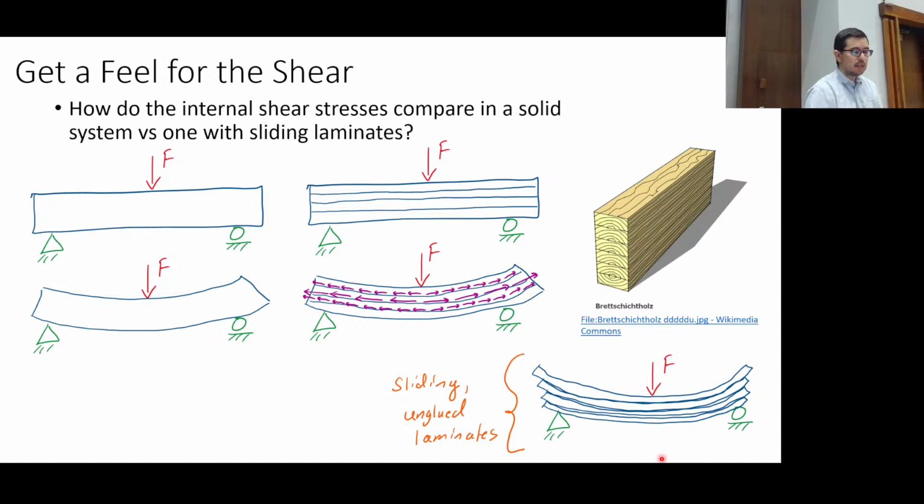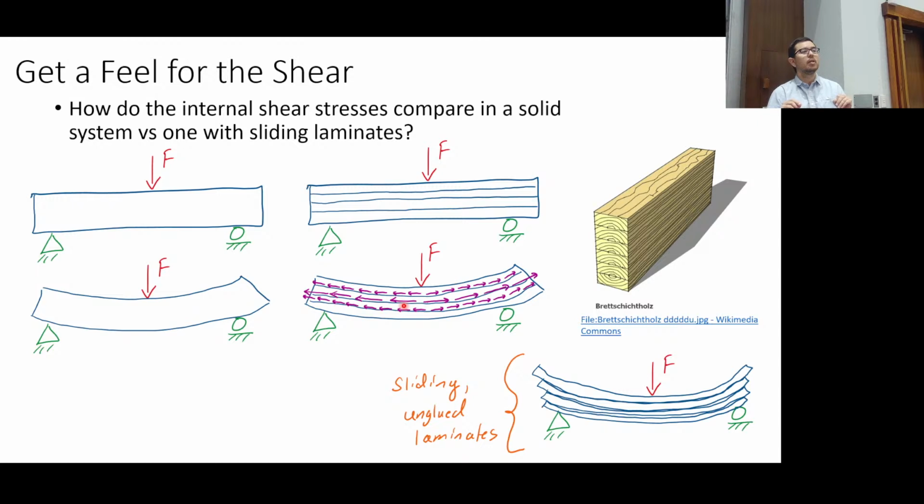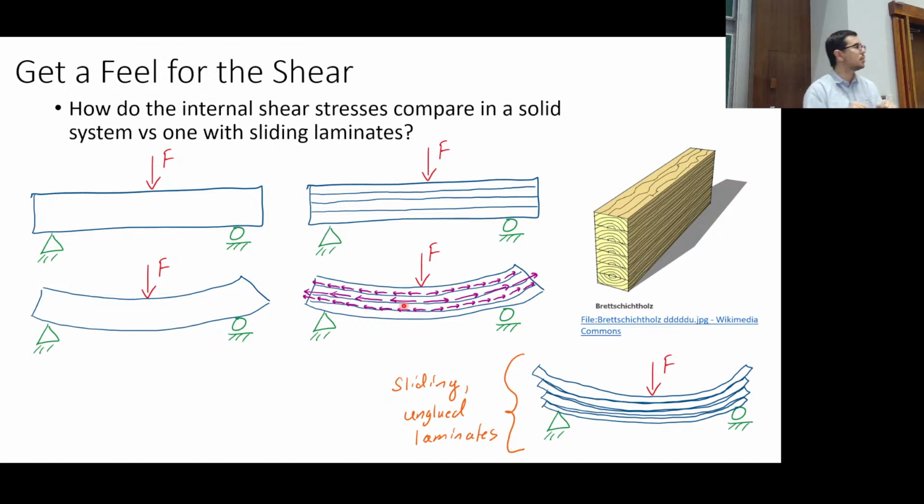In a little bit, you'll see that these shear stresses actually are maximum at the middle, or on the longitudinal or neutral axis. This is opposite of bending stresses.